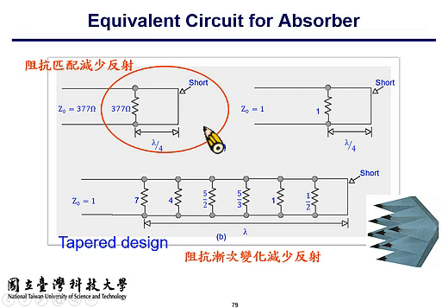So in fact, in an anechoic chamber, we do have a tapered transmission line approximation. We use pyramid-like absorbers to perform a gradual transition in the reflection coefficient, in the input impedance.